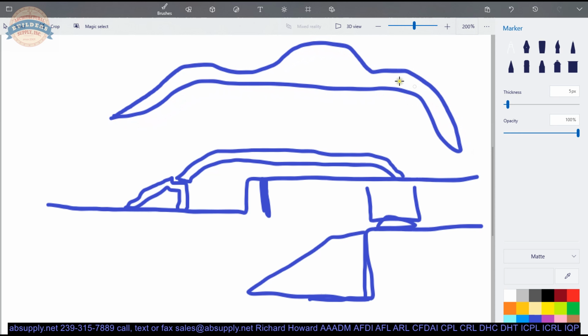Sorry for the poor drawing. That's a vinyl insert is what I'm trying to draw here, and it's like 1.5 inches overall height. But the client would need to rip that leg off and take all of this portion and install it here. Well, it's no longer fire rated. And I can't, these all 177 are fire rated openings. I can't advise the client to modify that threshold, even though that's exactly what he's pulling out.